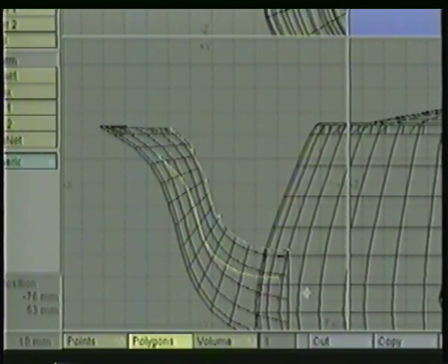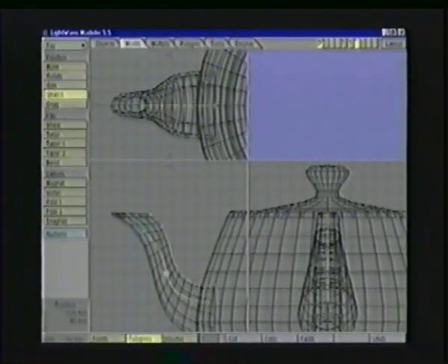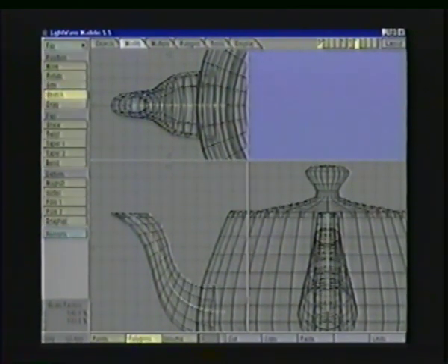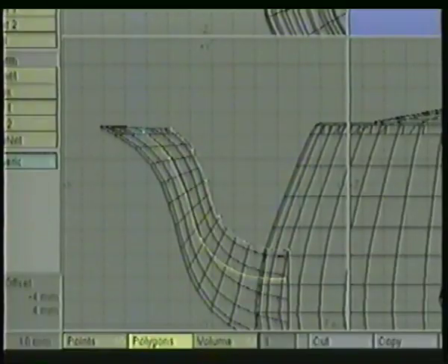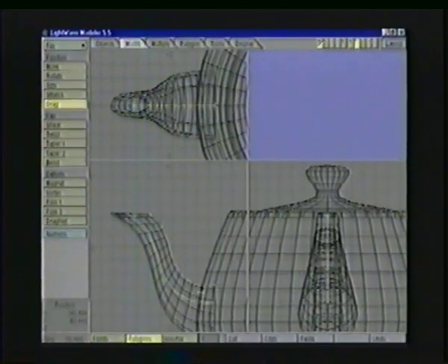You can see it's not exactly the right shape. It's a little small, so instead of dragging points manually one at a time, I'm going to go to Stretch, place my cursor about in the middle, and stretch upward, and then to the right. About right there. I'll hit T again for move and reposition it. Now at this point I'm pretty close, so I am going to go ahead and just drag these points back down to the middle. And we're not too bad, that's not too far off.